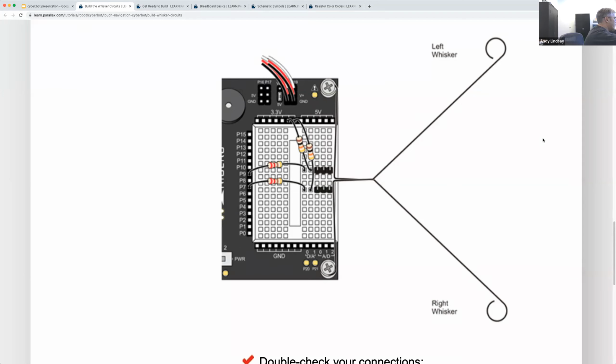Now be very careful about which row of 5 you put the parts in. Most importantly, that you get the same part in the same row of 5 as shown in the picture. I actually count down from the top and then insert my first 3-pin header, and then skip 2 more rows and then insert the second 3-pin header.